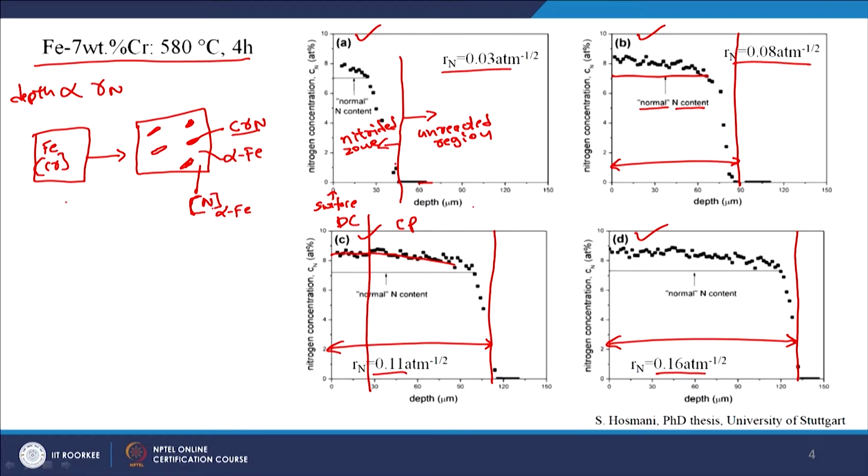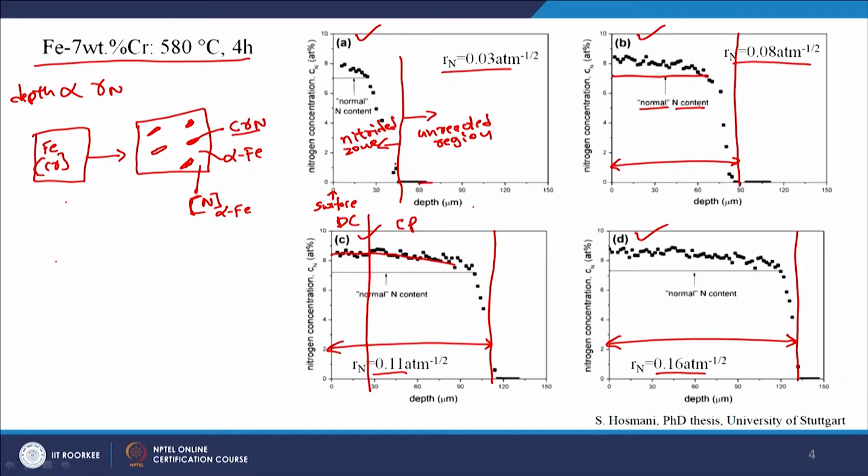In this case we have applied some temperature, 580 degrees Celsius, and for example a constant nitriding potential. So, we have seen in our first lecture that temperature and nitriding potential will set the equilibrium level of nitrogen which can be dissolved in pure iron, that means a fully ferritic iron. Okay. So, that condition can be imposed from thermodynamics,